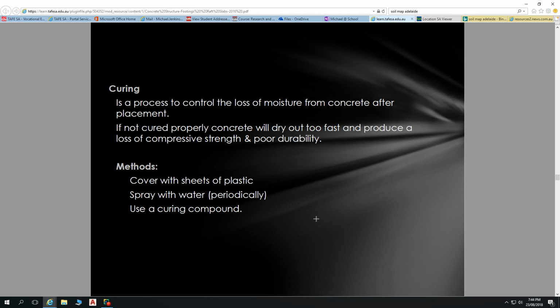Where you've got aggregates and it's cut away to show that aggregate. Or you can also work your aggregate down a lot with a steel trowel, get a really glassy finish and just touch it up as well. Polish that top off so you don't have any exposed aggregate, but you've also got a very, very smooth finish.